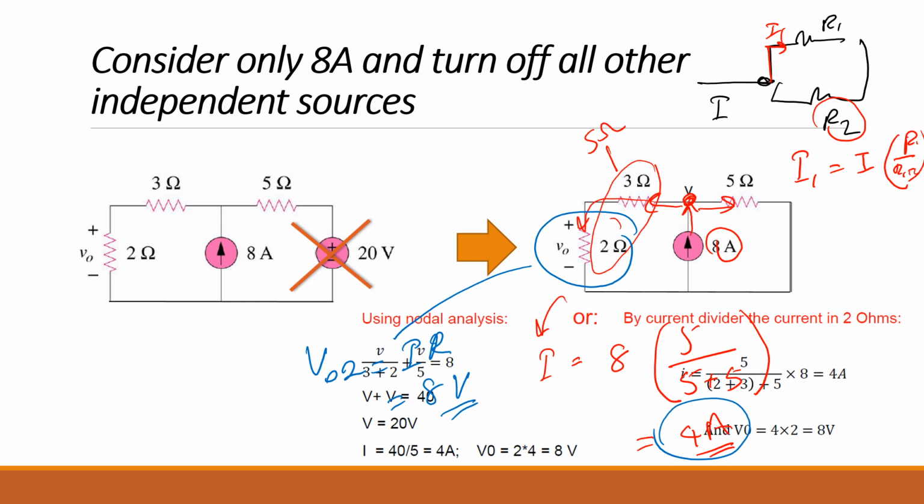So how do we know the direction of the positives and negatives? So positive side is this. Current should come to the positive side of a resistor. So because V naught 2 is positive, and also V naught 1 is positive because it was going towards the positive side. Am I right? When the current is going to the positive side, the voltage is positive. I told you that. So the total combined effect of both of these will be V naught equals V naught 1 plus V naught 2.